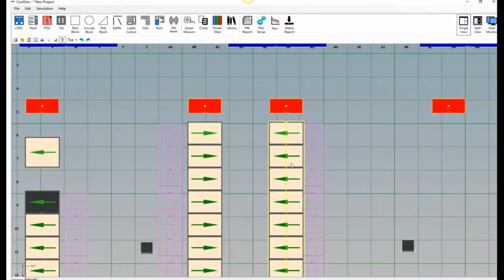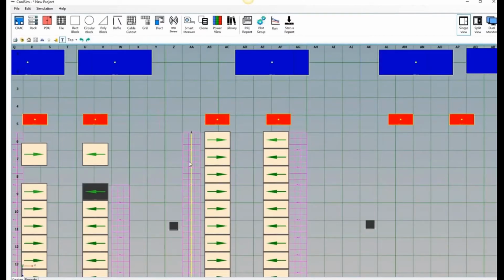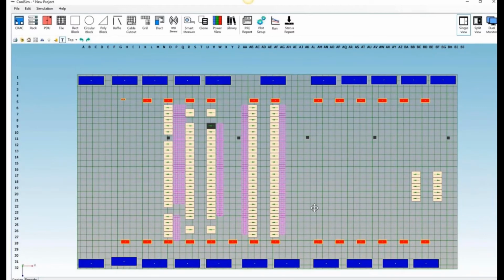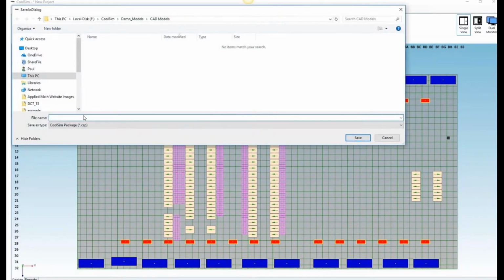We have an alignment tool, so I grab that one, Control-C, grab that one, put my cursor over the one I want to hold constant and say close gaps, in this case X. Do the same thing here, close gaps in X, and it will line those up perfectly. Now maybe they weren't, and so you want to leave them, but if you do want to line them up, do it, because the mesher will be happy and it will run faster.